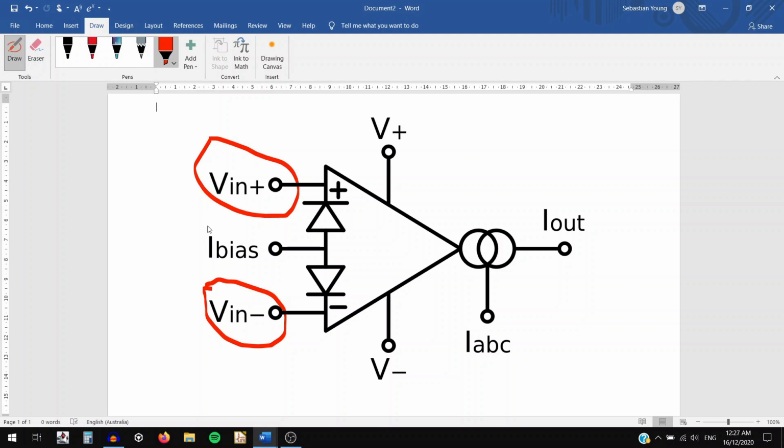In the middle here, we have this pin known as the diode bias, which can be used to improve the linearity and distortion when using a bit of a higher voltage into the inputs. Generally though, it isn't really needed if the voltage is kept between 10 to 20 millivolt. At the top and the bottom here, we can see our power pins, which can be used with both single rail and dual rail power supplies.